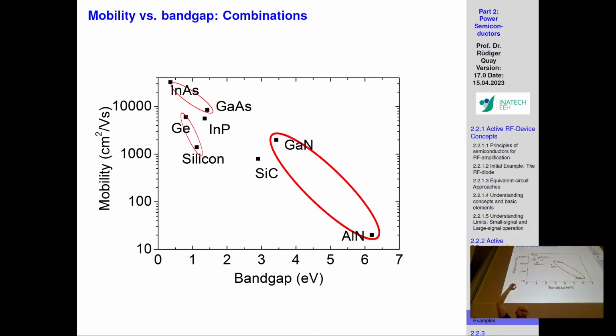Carrier mobility, we talked about fT and fmax: maximum current gain, maximum unilateral gain, or maximum power gain. And these depend on frequency. If I draw a frequency chart, and this is 0 and this is 10 terahertz or whatever, or 1 terahertz in this case, it means that my gain reaches 0 far sooner than it would if I have a higher mobility. But having a higher band gap means that you will have more power, which means that you can make a compromise. Hey, I'm not designing a circuit that works at 1 terahertz.